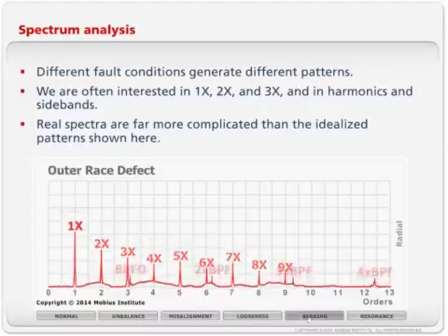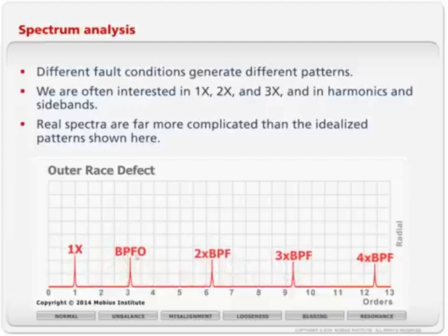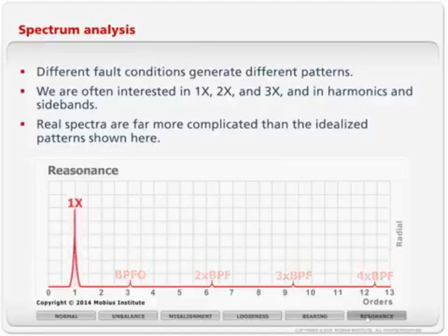If we had a fault with the bearings, okay, there's that green peak we talked about, but it's really common to see a peak at twice that frequency, BPFO, that should say 3 times and 4 times. We can have a problem called resonance, and that might also make that peak go up, but the base of the peak broadens out. Anyway, the key takeaway here is that the spectrum tells us about the nature of the fault and the severity of the fault.